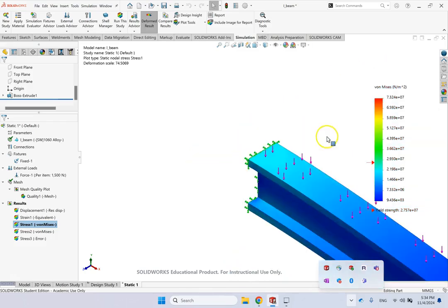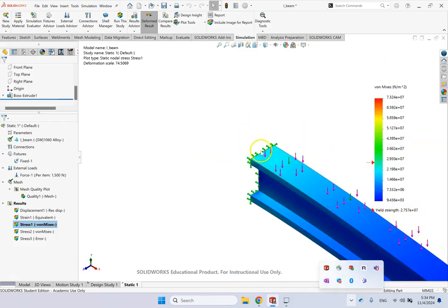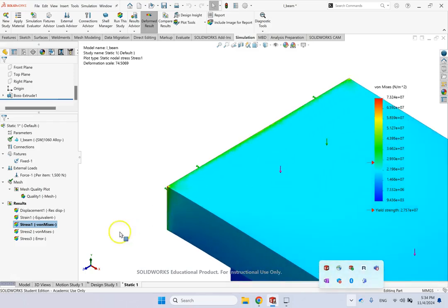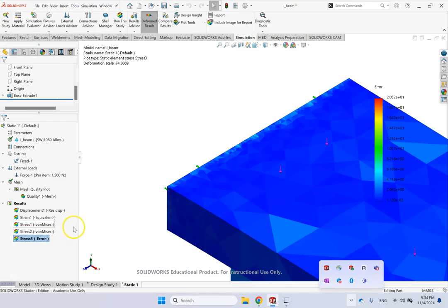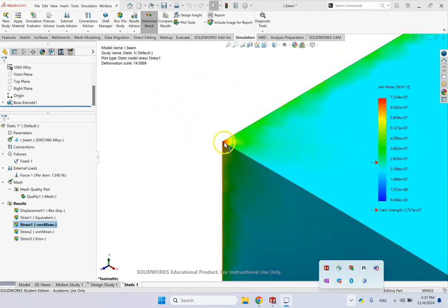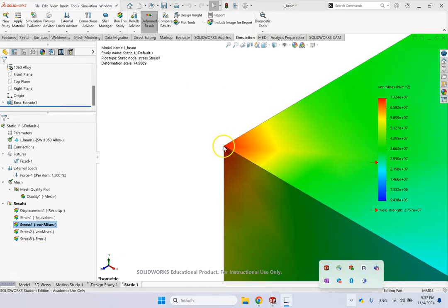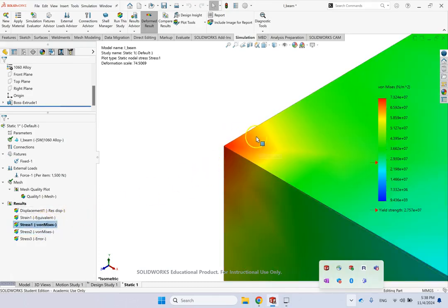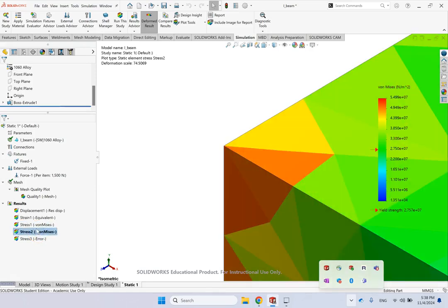It's much smoother. And you see a very smooth transition here, red, blue, then those numbers. Okay, so you see it's much smoother now. And if you look at the energy norm, look, this is down to only those few spots of 20%. And those are these corners where you have some numerical calculation errors. Okay, so here you can see that if you look at the element wise versus nodal, you see there is a discrepancy here. There is a difference.